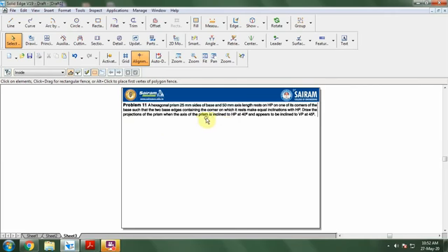The second position is given with respect to HP at an angle of 40, so the axis is inclined to HP at an angle of 40. Coming to the third position, the axis is inclined to VP at 45 degrees. They clearly specify that it appears to be inclined to VP at 45 degrees. So appears indicates it is an apparent inclination, so no need to calculate the beta angle.